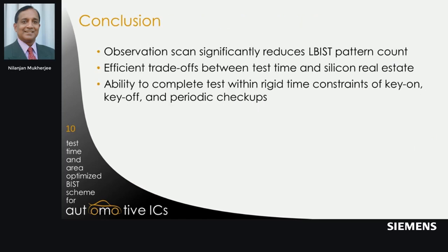In conclusion, observation scan helps in significantly reducing the LBIST pattern count for in-system testing. It gives one the flexibility to optimize between the test application time and silicon area overhead. It also helps one meet the stringent time requirements for logic testing during key on, key off, and online monitoring.